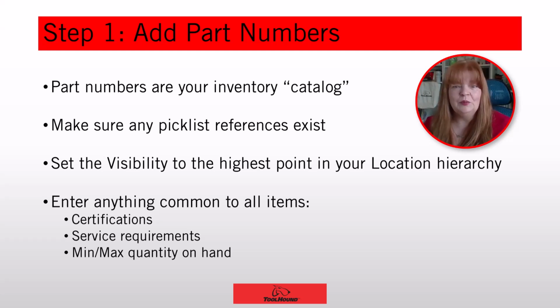If you want to add any pick list references to your part numbers, such as a new manufacturer or vendor, add them first so they're available when you add the part. With an established database, this is less of a concern.